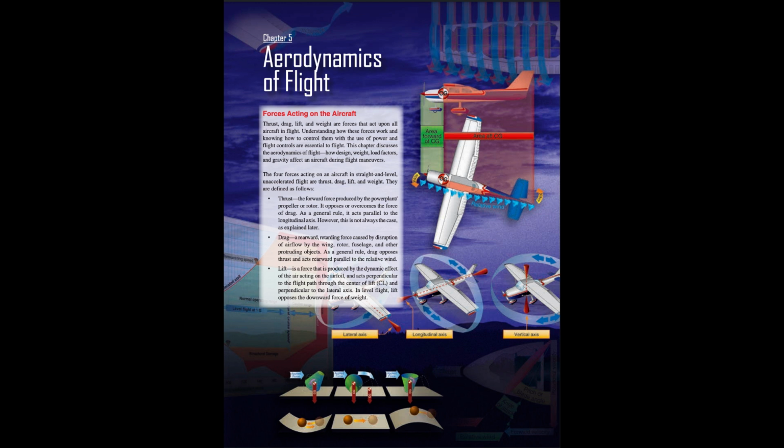2. Drag, a rearward, retarding force caused by disruption of airflow by the wing, rotor, fuselage, and other protruding objects. As a general rule, drag opposes thrust and acts rearward parallel to the relative wind. 3. Lift is a force that is produced by the dynamic effect of the air acting on the airfoil, and acts perpendicular to the flight path through the center of lift, CL, and perpendicular to the lateral axis. In level flight, lift opposes the downward force of weight.